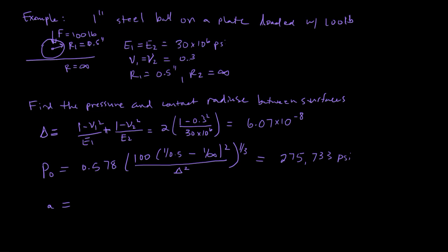And we can calculate the contact radius between the surfaces. It's 0.908 times our load times our contact modulus, divided by 1 over our radius for one plus 1 over the radius of the other, which is infinity, to the 1/3 power, which is equal to 0.013 inches.